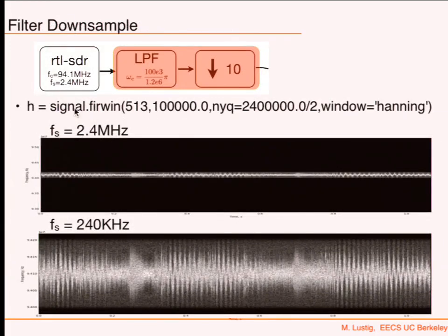So first of all, you're going to design a filter which has 513 taps. It's actually, the order of it is 512, and we'll differentiate that when we talk about filter design. The order is called 512. The length of the filter, how many coefficients it has, is actually 513. In MATLAB, if you want to design something, you have to specify 512. In Python, you have to specify 513. They'll give you the same filter. Okay, so there are some nuances that you have to think about.